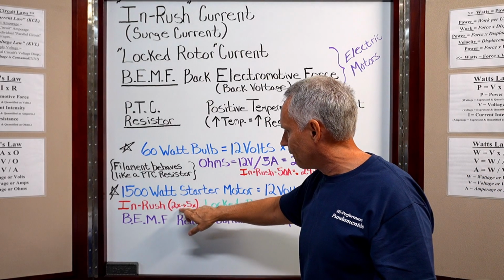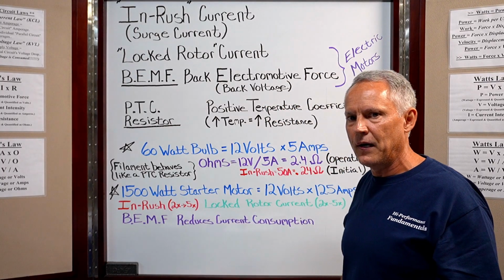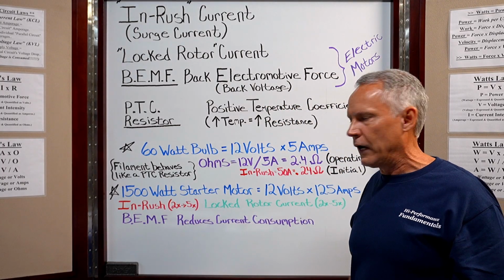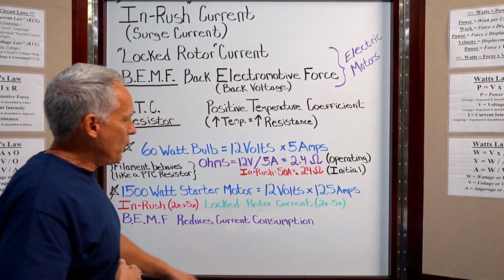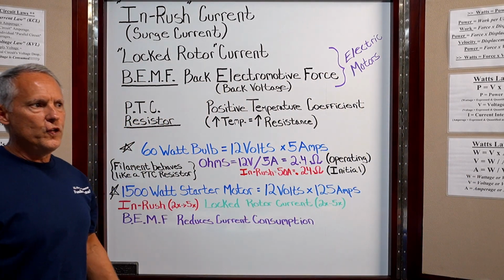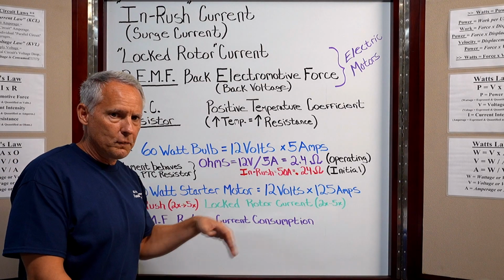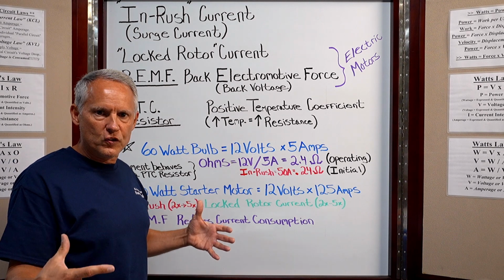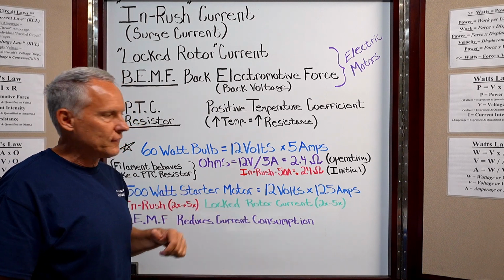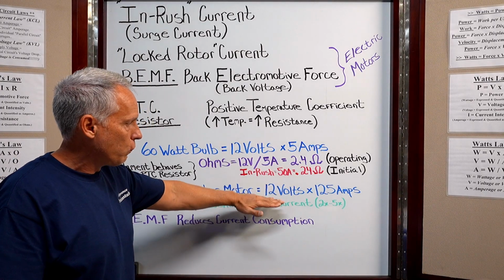Okay, I'm probably going to factor in something in the order of about 2.5 times, maybe 3 times that much, so that my circuit can easily carry that kind of a load. Another thing to consider is that anytime you have an energy source like a battery and you are utilizing that energy source, this voltage, we had talked about voltage as voltage pressure, and a battery as an electrical energy storage device, right? As you utilize some of that energy, the pressure will drop some. So the voltage will drop.